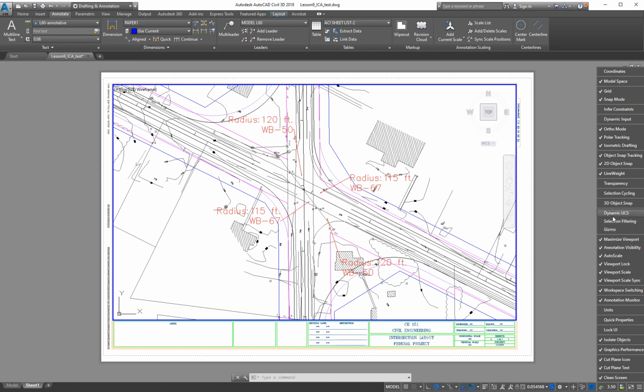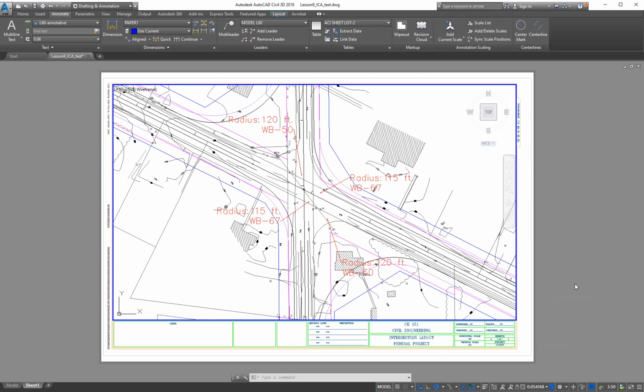A lot of you had trouble before with dynamic input or not dynamic input. You can turn that button on and off up here. This is how you turn on and off all the stuff you see along the bottom in these toolbars. So just make sure viewport scale is on. It is by default, but just in case, because everybody had to download this and there are probably a bunch of different versions hanging out there. So this is our viewport scale. It should be on already. If it's not, go over here to the far right corner and turn it on.